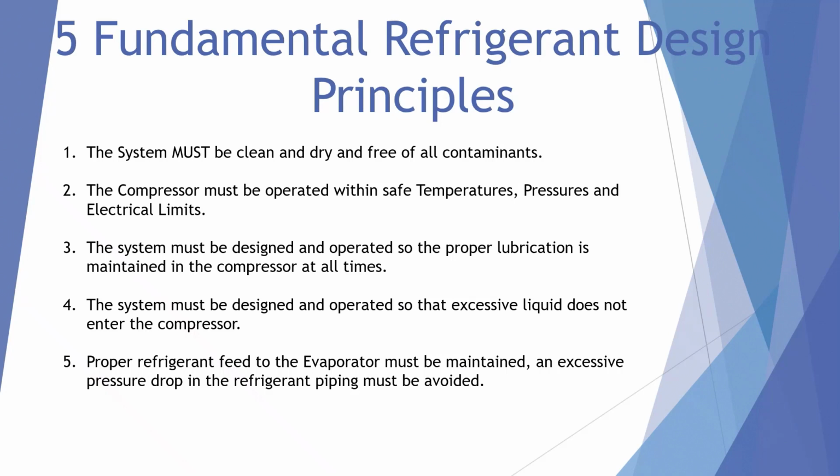There are 5 fundamental refrigerant design principles that every technician should follow when installing a refrigeration system. Number 1, the system must be clean and dry and free of all contaminants. Number 2, the compressor must be operated within safe temperatures, pressures, and electrical limits.